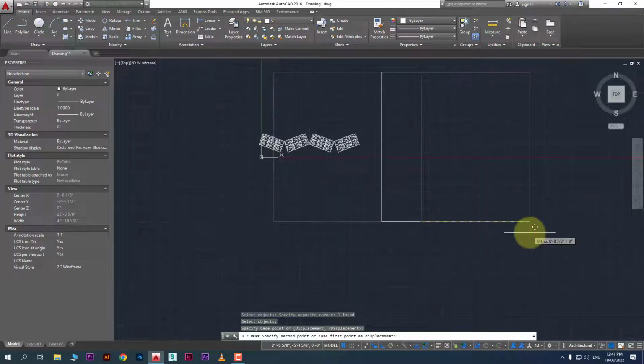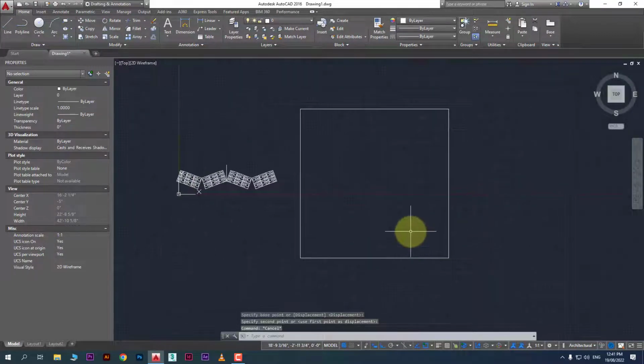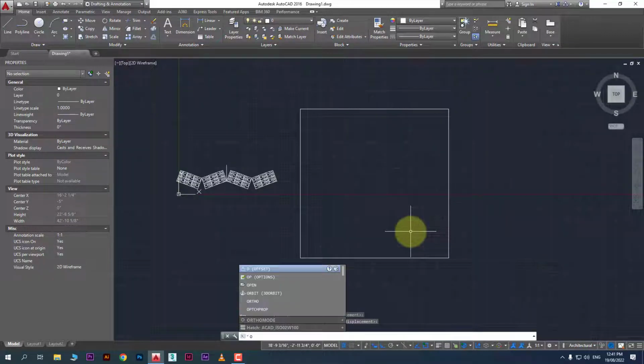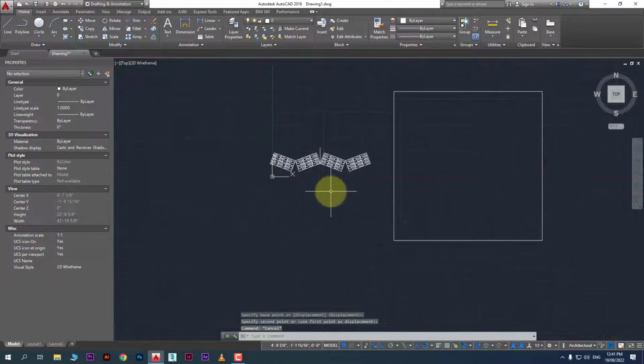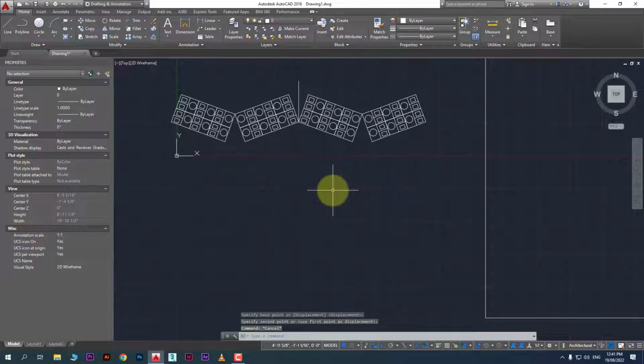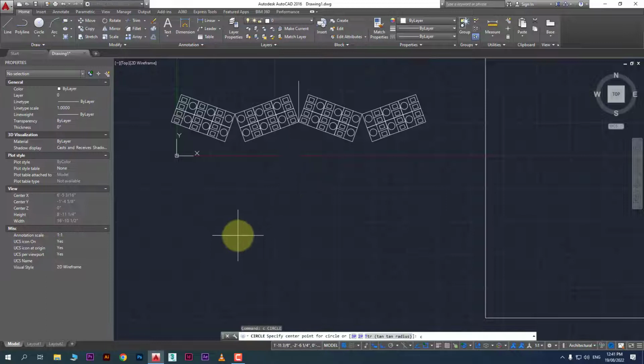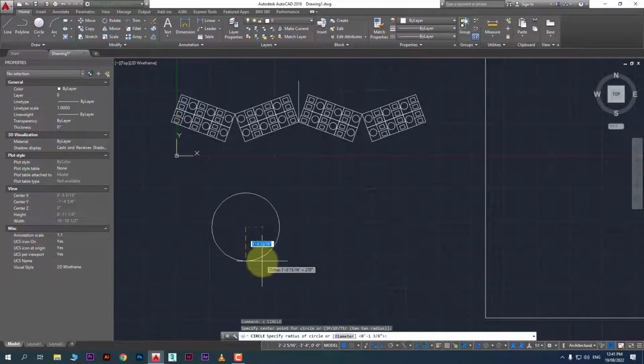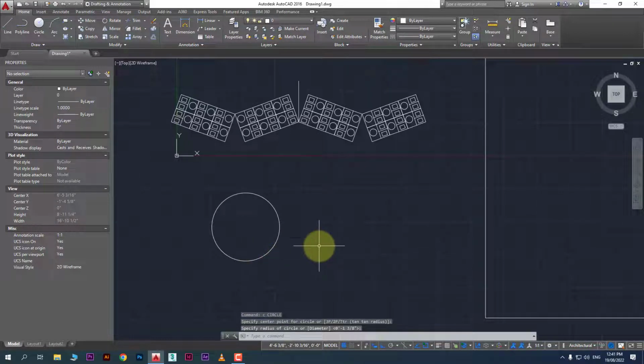So what I will do is create a wall outside, using offset. Let's look at the offset command. Okay, the next command is offset. Then we will use it to create a room as well. The shortcut key for the offset command is O. The offset command is used to create a parallel copy of an object, or we can say a copy of the object at a parallel distance.